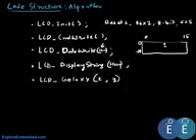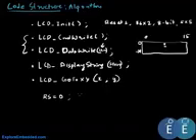Now let us look at lcd data write and lcd command write. These two commands are used by all the other commands in the library, if you look at the structure, to do all the functions. Now lcd command write is pretty simple. Since we are writing a command, we do register select as 0. Read write, since we are writing, becomes 0.